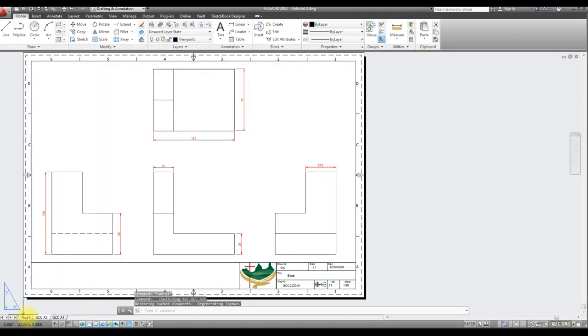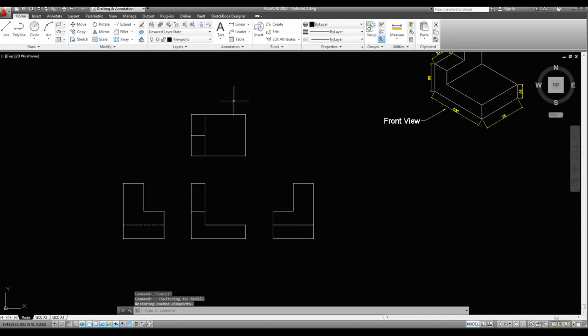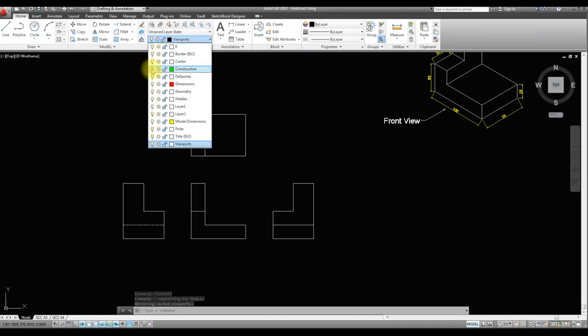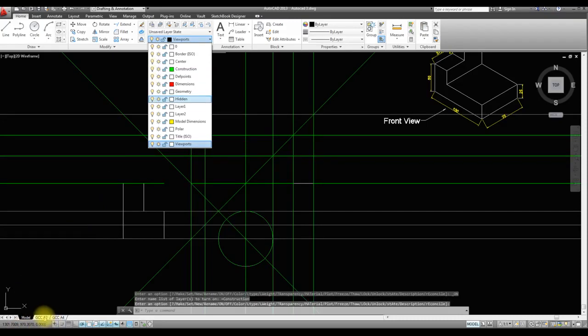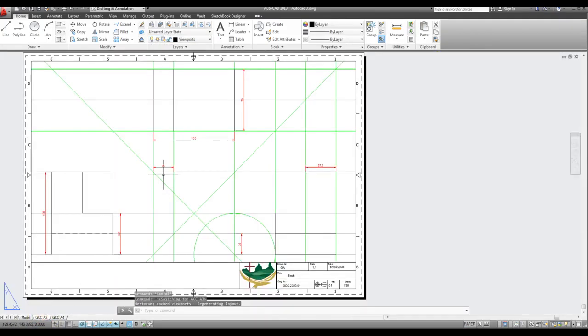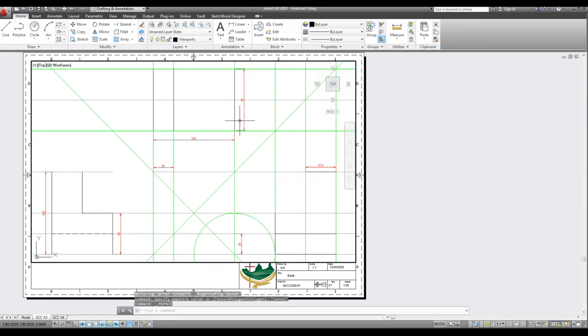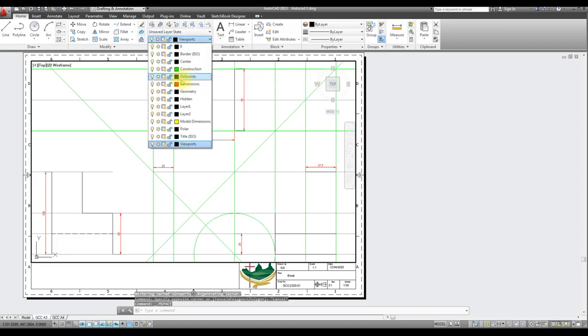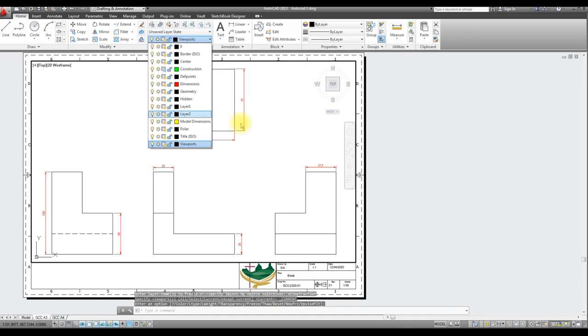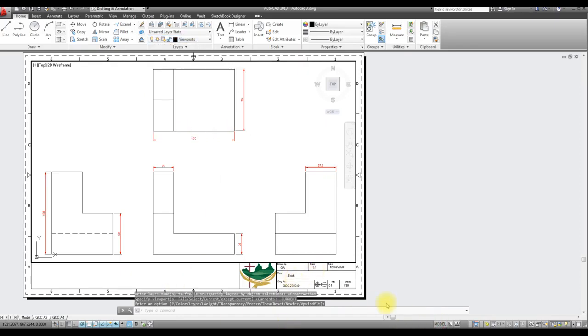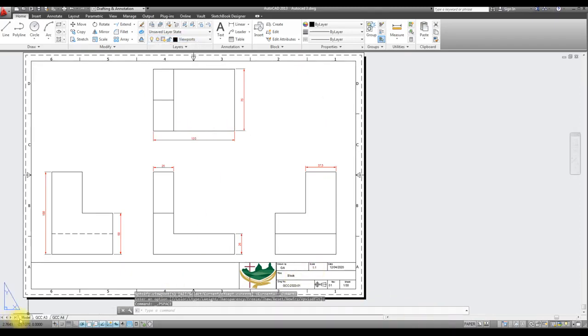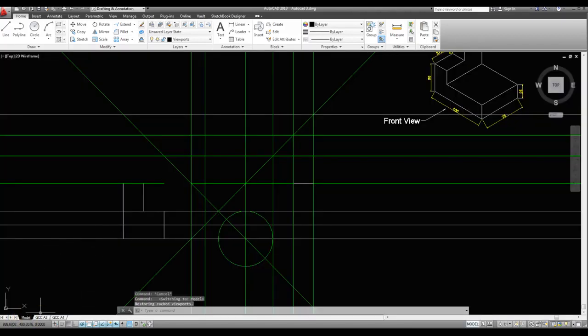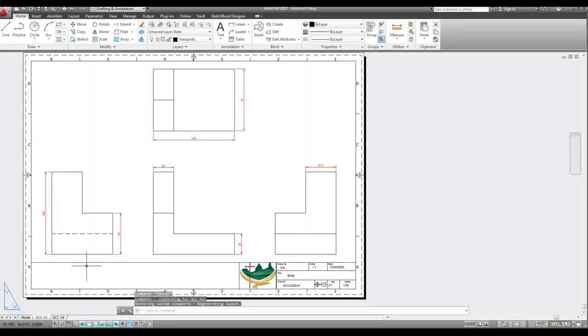It's not in the drawing, yeah, that's great, but in our model space we can't see. We don't have our construction geometry anymore. We need our construction geometry. If we go back into our sheet, this is another advantage of layers, and we've got it on a layer. If I double click inside the layer, we're in the model space again, what we can do is this tool here, it's freeze or thaw in current viewport. Click on that and it goes off. Go back into paper space. It's still on in model space, but it's not in paper space, and that's why we put things on layers.